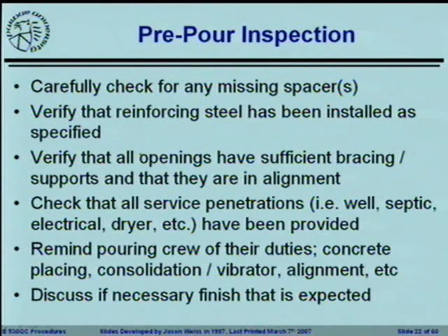So, pre-pour inspections, a couple of things that we really need to make sure of. Checking for any missing spacers. You really want to make sure that your reinforcing steel is going to end up where it needs to end up. Make sure it's tied in. Make sure that it's not flopping around in the breeze.